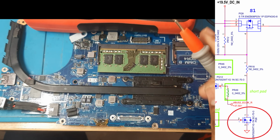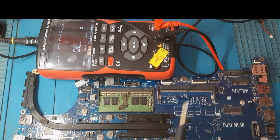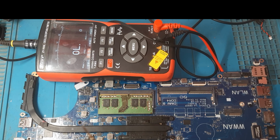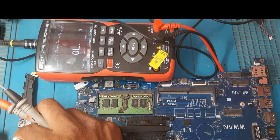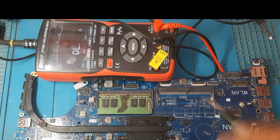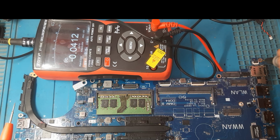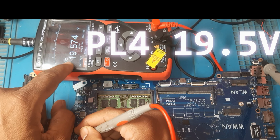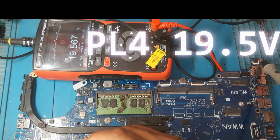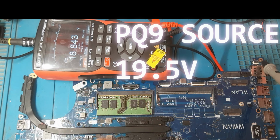Okay, so now I will give the supply and show you whether the gate voltage is present or not. Just a minute. Here, see, I am going to connect it. Connect it. So now 19 volts. Check the multimeter. Here is the PL, the main supply coil. First it's coming 19.5 volts. Okay, after that, the source which I showed you now, the source is 19.5. What about the gate?